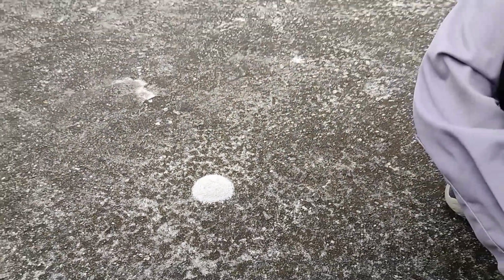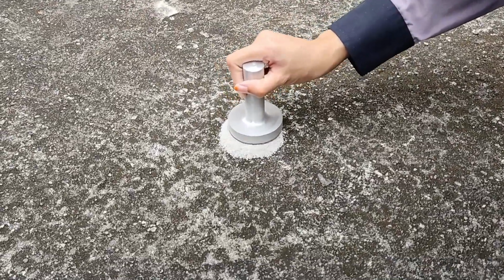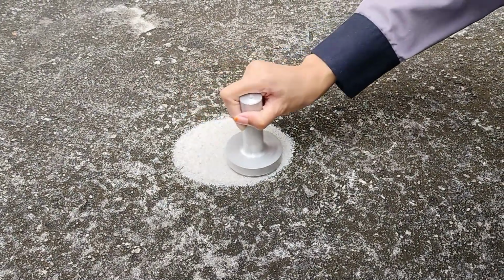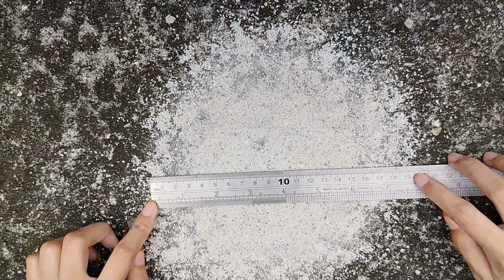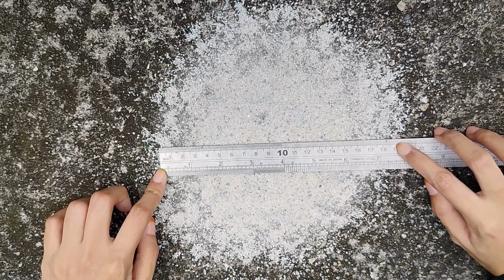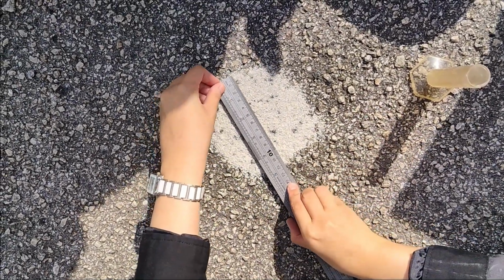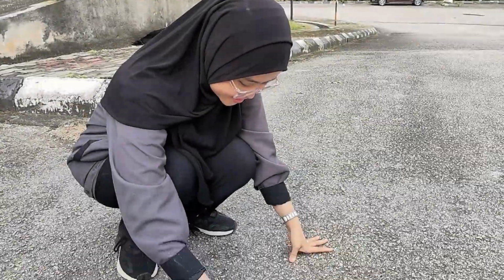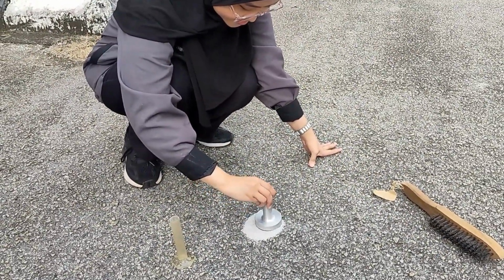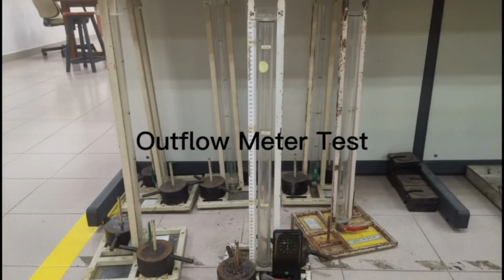shape. Flatten the heap of sand in a circular motion as thin as possible using a steel pad. This step is done until the sand fills in all the voids of the pavement surface. Then, check for a center point of the circular sand patch made and measure its diameter at 3 different locations. Record all 3 diameters and compute the average diameter. Repeat all the steps from the beginning until the diameter of the circular sand patch is taken at rough and medium surface. We conduct outflow meter test.